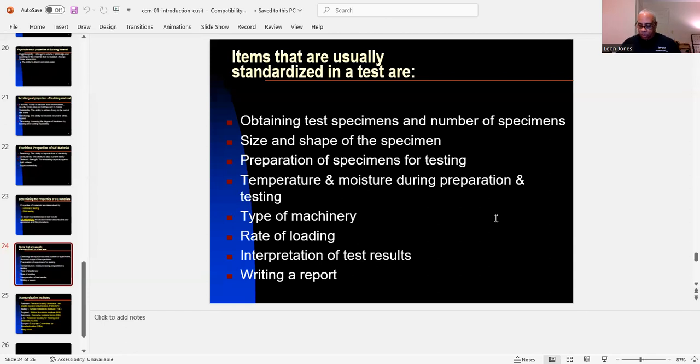Well, what am I doing? Well, I have my thermometer out because I'm going to take the temperature. I have my air meter out and I'm going to weigh my air meter because we're going to do what we call a water cement ratio in the field. So I'm going to measure my bowl to my air meter. I have my cylinder molds ready because I am actually going to use concrete to make the cylinders for compression testing. Also want to have my slump cone and my tape measure. That's what I'm talking about, preparations.